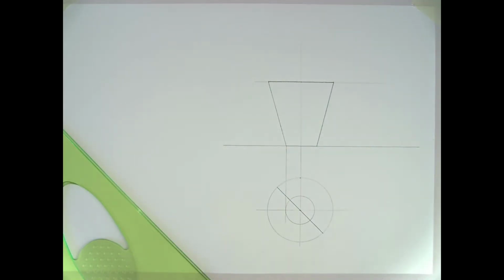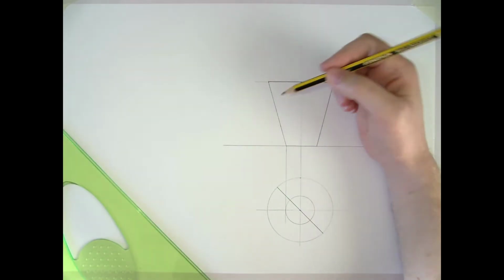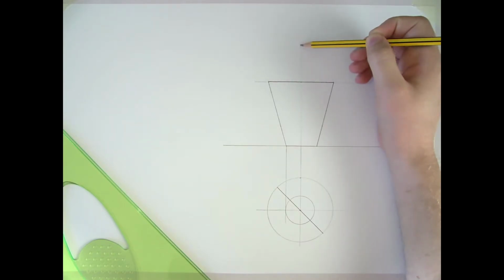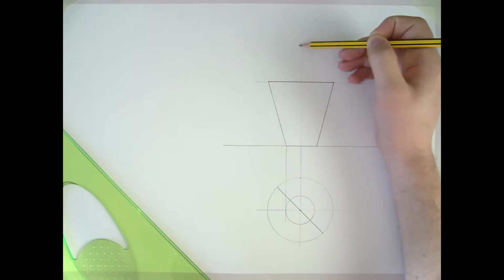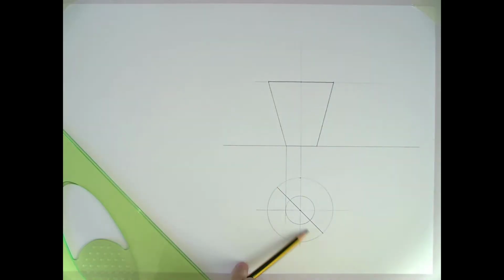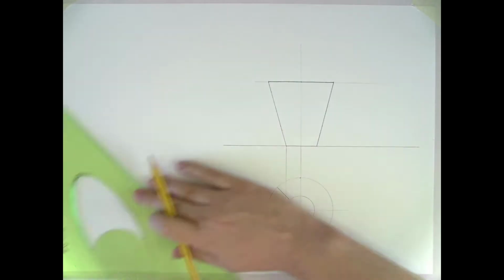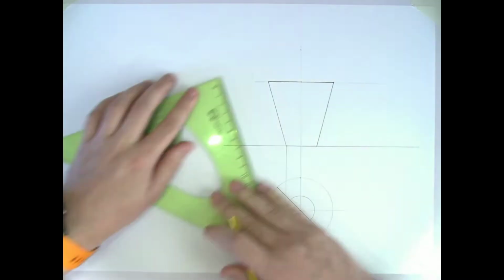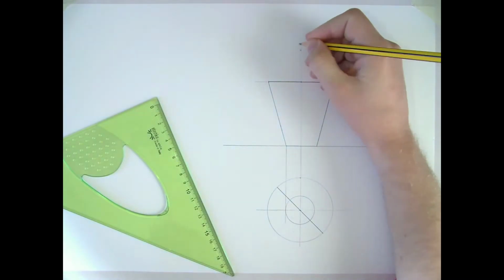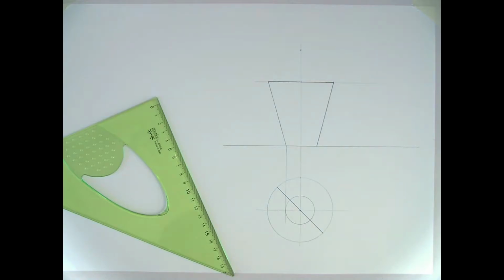So for our handle up on top, we're told that it's semicircular, which means that the very top of this is going to be equal to the radius of this. So how high up this goes, if we were looking in at the bucket this way, we would see it as a semicircle. So from here to here is radius 35, up to the point on the top would be 35. So up here is going to be up 35 millimeters. So that's the top point, and it is also the end of the major axis.